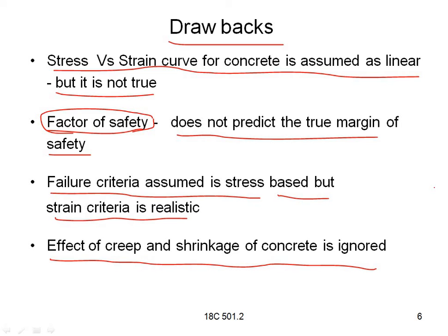So when a time dependent deformation due to sustained loads is acting, creep is indicated when the strain in a solid increases with time, while the stress producing the strain is kept constant. Okay, so that is the creep here.